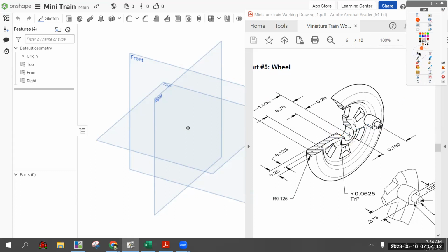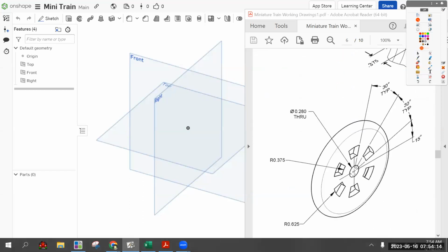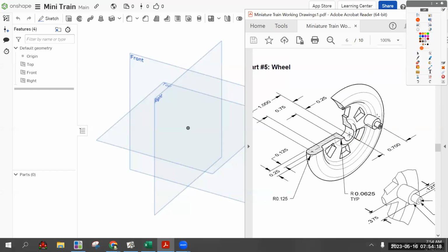We would have to figure it out based on the size of the through hole from the back. We would have to make a gap that's half of the diameter before we start drawing. So it's actually going to be easier to ignore the center hole until we actually have the full revolve, and then just make a circle that's centered and cut it out.